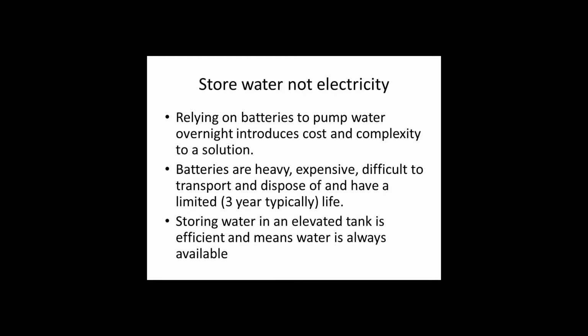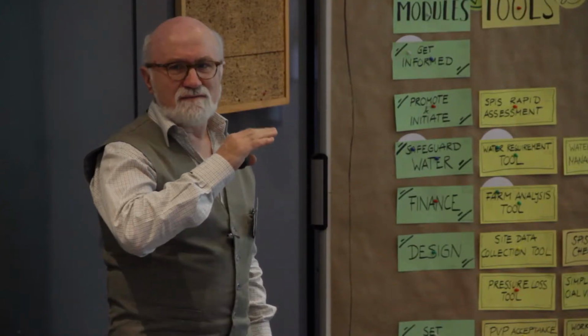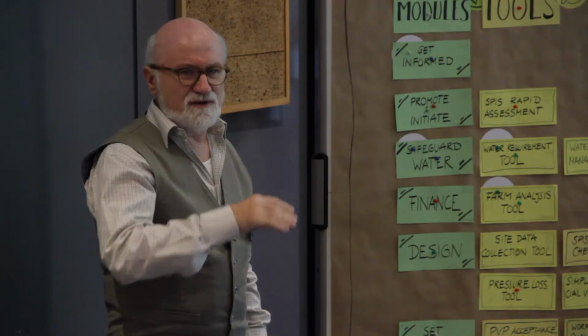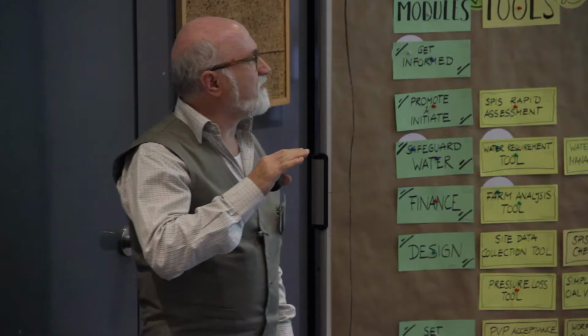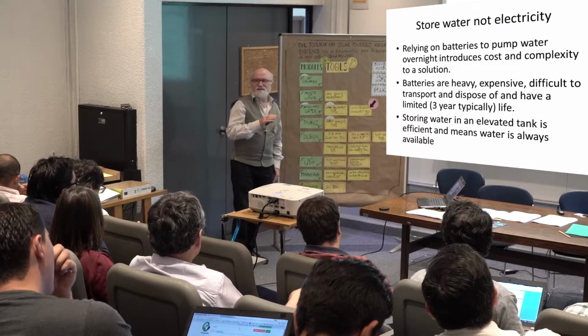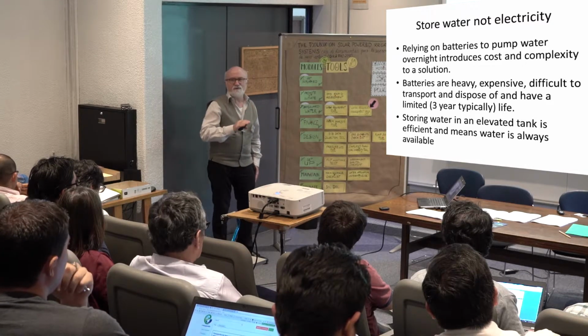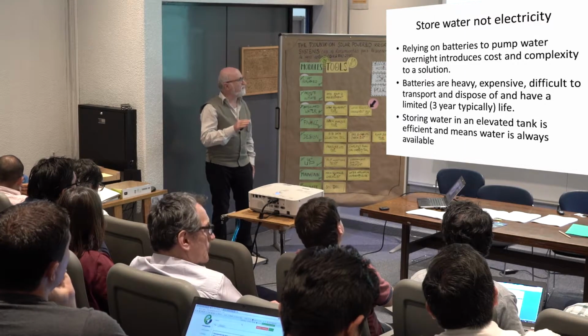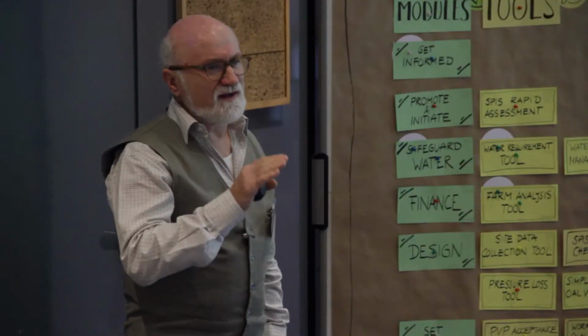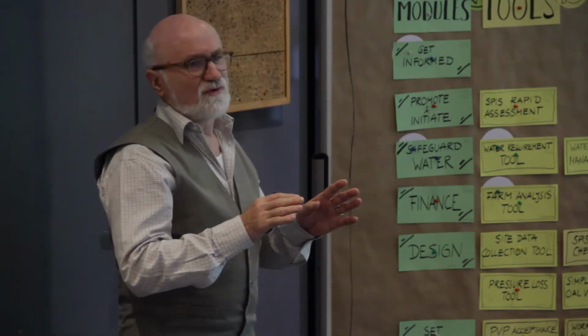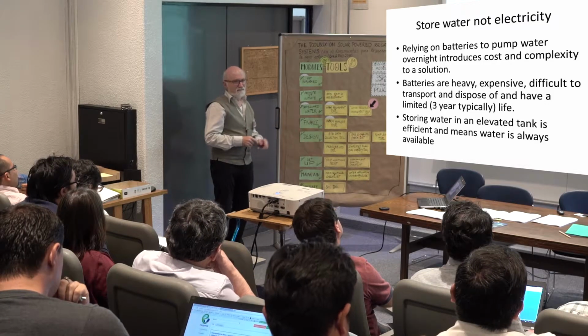And as you have seen, the voltage is changing during the day. So in almost all cases, these pumps and controllers have no battery, because the battery needs constant voltage. So try to avoid batteries, and all pump manufacturers, if you use a battery, will give you no guarantee if you manipulate it. So if you need solar energy for lights for your house, have a separate panel, and don't try to do everything on the same system.